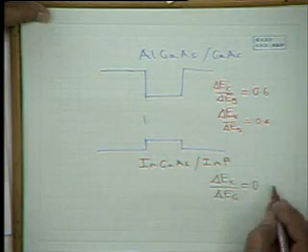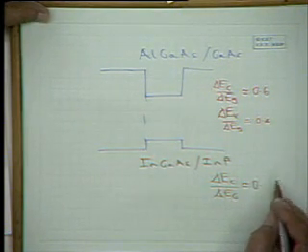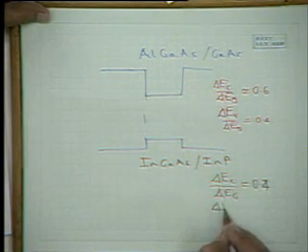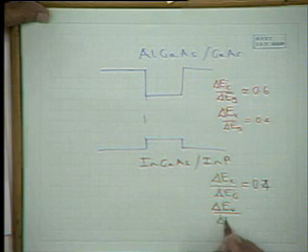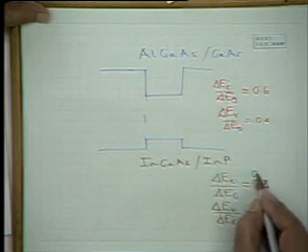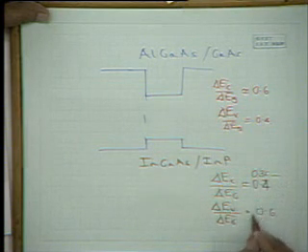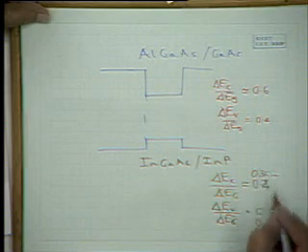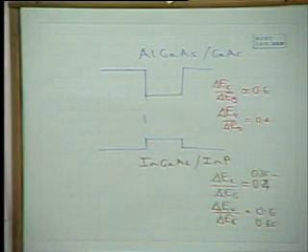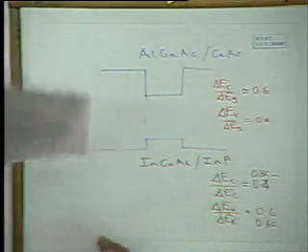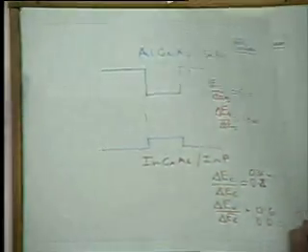about 0.35, or you can say it's the opposite: delta EV by delta EG is about 0.6. This is really, it could be 0.35 to 0.4, and this is 0.6 to 0.65. Okay, one-third, two-thirds type of thing. So that depends. That determines the wells in the finite quantum well.